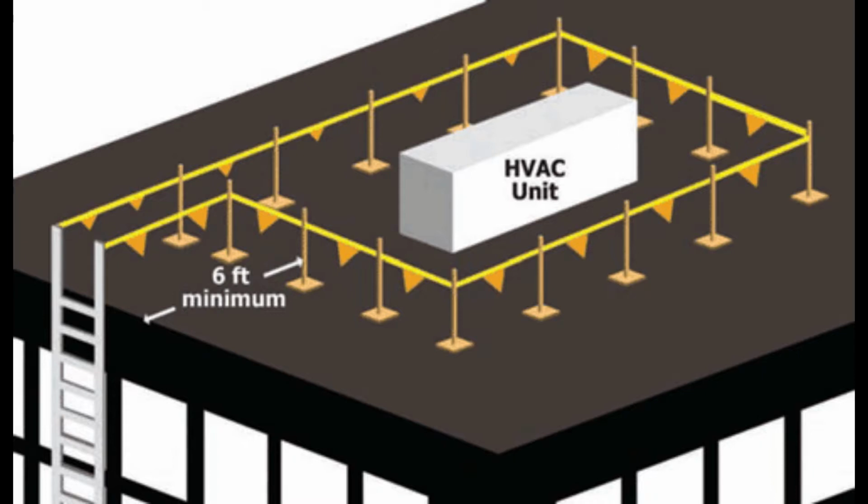Additional control lines shall be erected at each end to enclose the controlled access zone. Only employees engaged in overhand bricklaying or related work shall be permitted in the controlled access zones. Control lines shall consist of ropes, wire tapes, or equivalent materials and supporting stanchions as follows. Each line shall be flagged or otherwise clearly marked at not more than 6 feet (1.8 meters) intervals with high visibility material.